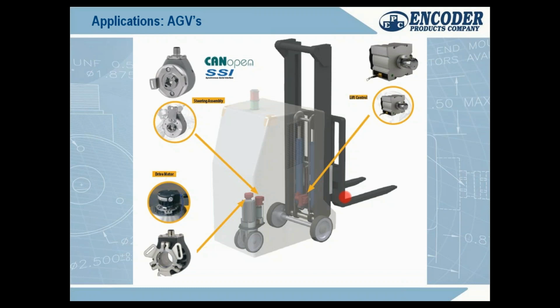There's a lot of push for safety in all industries. And now a lot of people have realized that, hey, we need to know the height of these forks even before we engage telescopes. If somebody has 2,000 pounds of load on these forks and they put these forks 4 feet up, this forklift, if it was manually operated, could still tip over. So even though it's still manually driven by a human, you will see encoders in these applications because it'll tie back to the governor and the control. The higher these forks, the slower the maximum speed of the forklift.